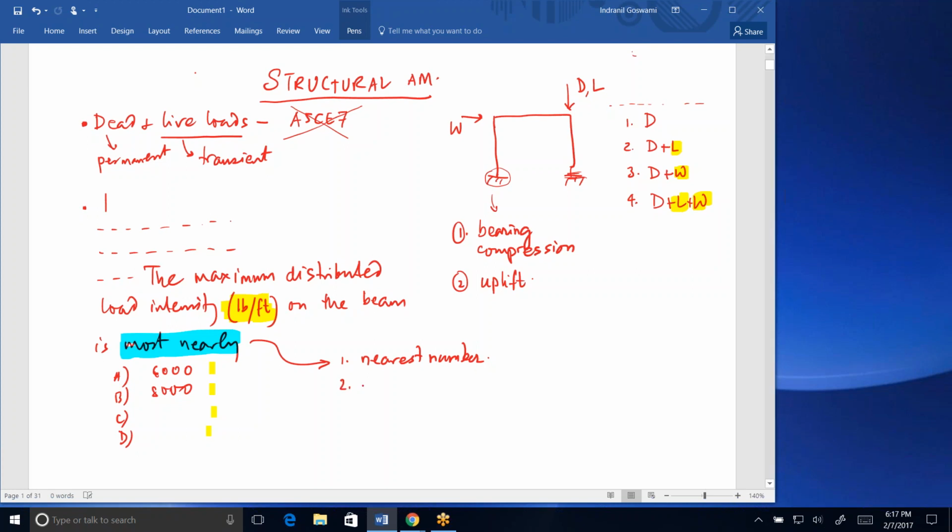The other option is when some kind of a strength issue is involved. For example, here, maybe the criterion in this particular problem was a certain deflection cannot be exceeded. And they're saying if the deflection is limited to this number, then what is the maximum distributed load you can put on the beam? In that case, you have to stay under the calculated value because the number that you calculated represents an upper bound. And for that distributed load, you will just hit the critical deflection. If the load is any heavier, the deflection will be exceeded, and it's not a strength exceedance, but it's a deflection exceedance. But sometimes you go lower, right? And sometimes you go higher.